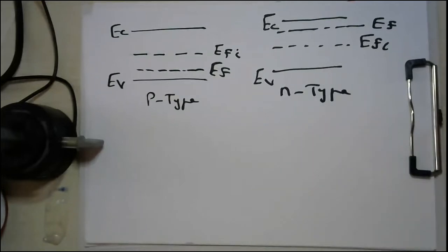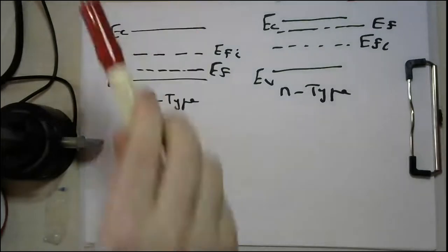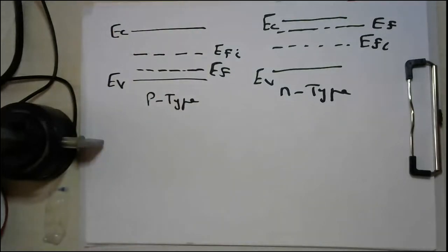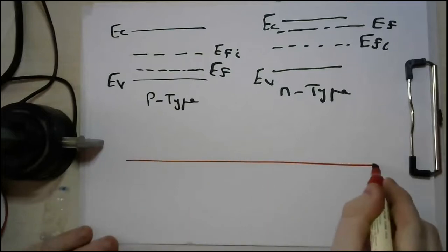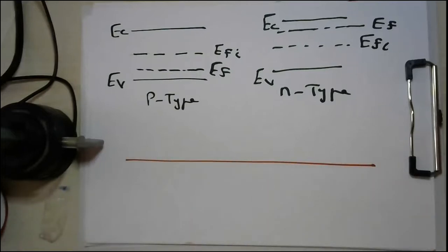As we agreed from part number 1, in order to combine both, start with the Fermi level. So first, draw this EF, and then start to sketch every line in your diagram with respect to this EF.